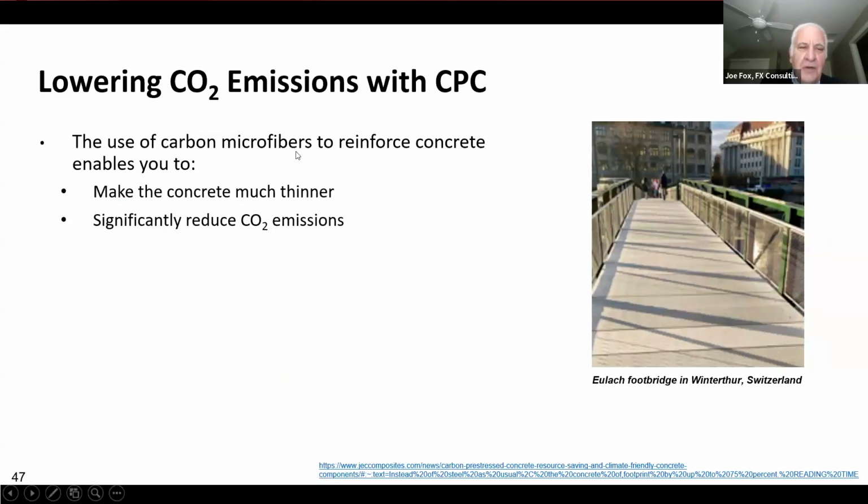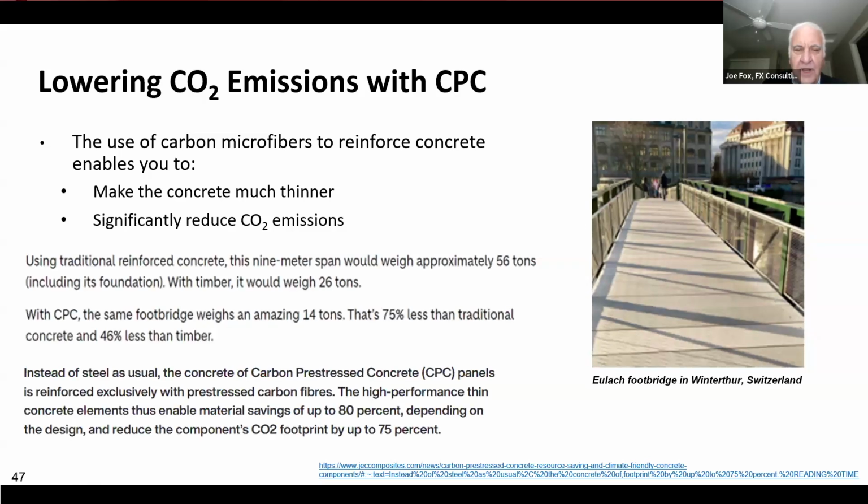Well, the use of those carbon microfibers to reinforce concrete enables you to make the concrete much thinner, and therefore significantly reduces CO2 emissions. Here's an example for this footbridge in Switzerland, taken right from their website. The footbridge made with concrete would weigh 56 tons, but with CPC, that's reduced to 14 tons. That translates into a 75% reduction in the CO2 footprint for this bridge. 75%.